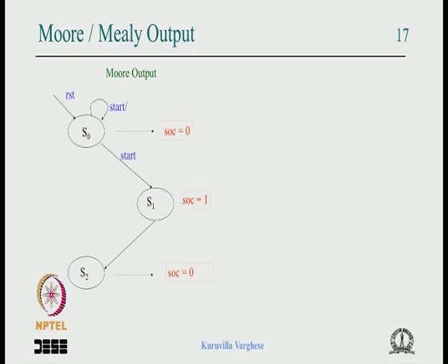But in practical cases there are, as I said, maybe so many states, maybe more than 20 states, more than 15 outputs, and some are Moore, some are Mealy. It's not some ideological matter of taste to choose Mealy or Moore output. It's not that you like Mealy or something like that. There are some cases where Mealy is the most appropriate thing, and some cases where it cannot be done at all. So you have to choose, and that is what we are trying to do.